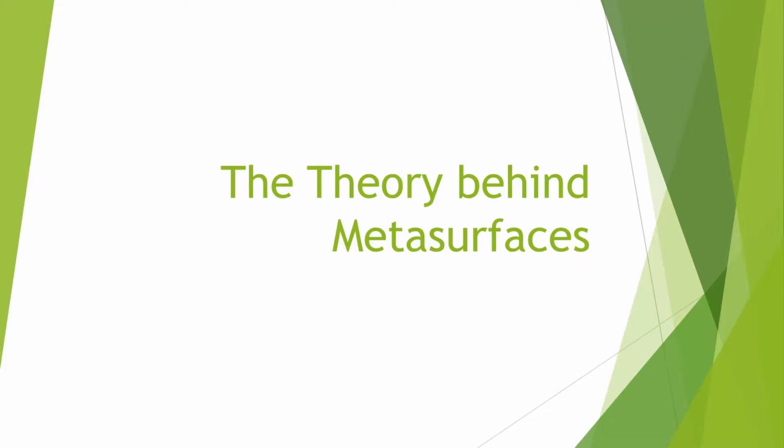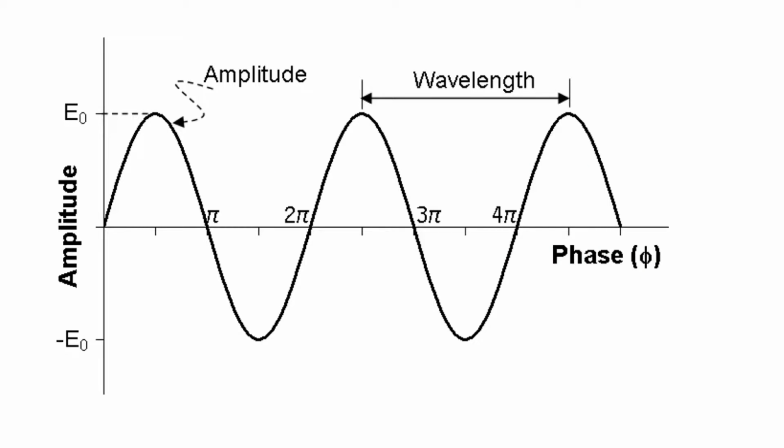I'm going to be talking about the theory behind metasurfaces. In conjunction with a metamaterial, a metasurface refers to a surface generated by a metamaterial. Like metamaterials, most forms of metasurfaces incorporate sub-wavelength structures into their design as a means of interaction with incident waves. They have the ability to produce abrupt changes over the scale of the incident wave's wavelength in either its phase, amplitude, or other associated characteristics.